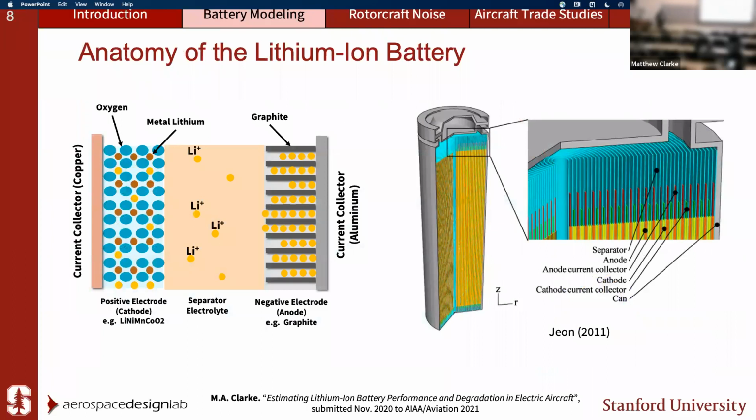So with that being said, I think the most practical thing to do is to step through what a battery really is. These particular cells are essentially jelly-rolled structures made out of five key components, and this is what I have here. You have the two current collectors on each side. Then you have a rock salt cathode, which is the lithium part. The anode is typically graphite. And then you have the movement of ions across an electrolyte, which is typically an organic solvent.